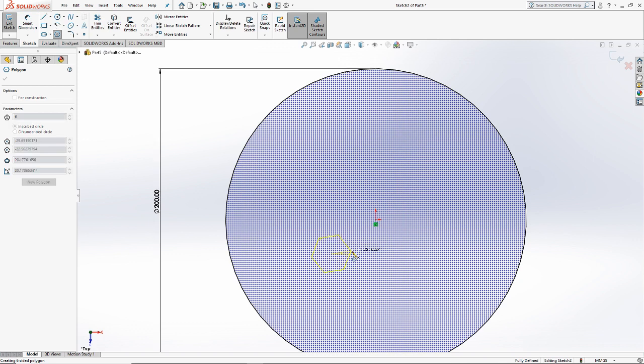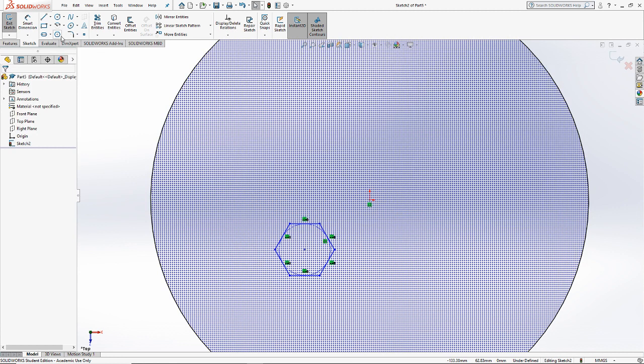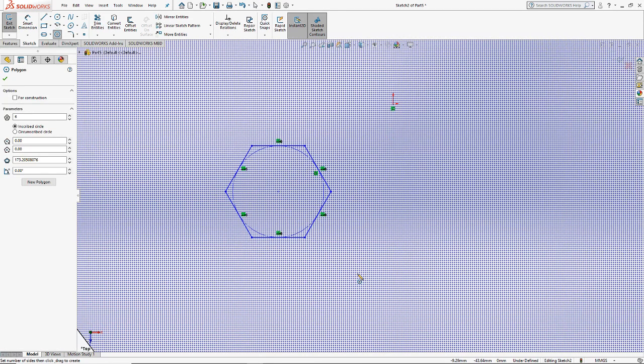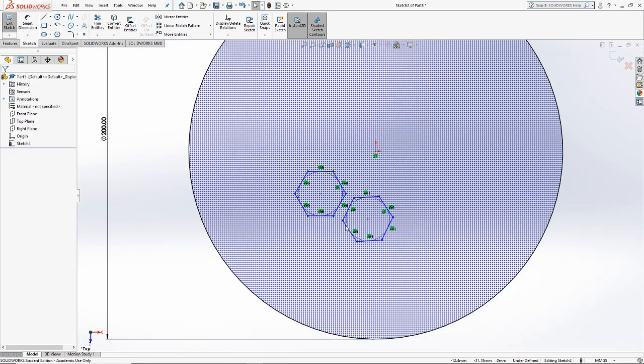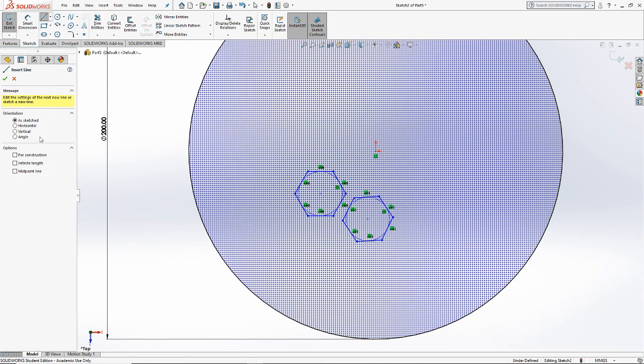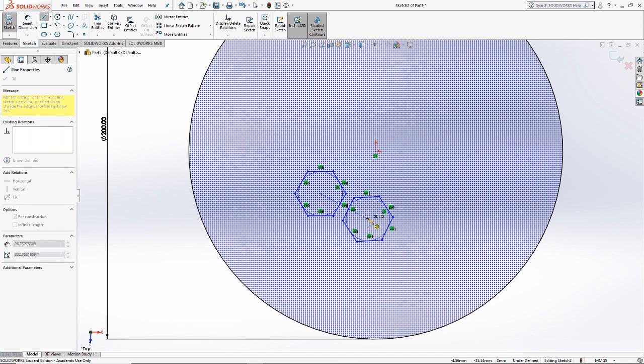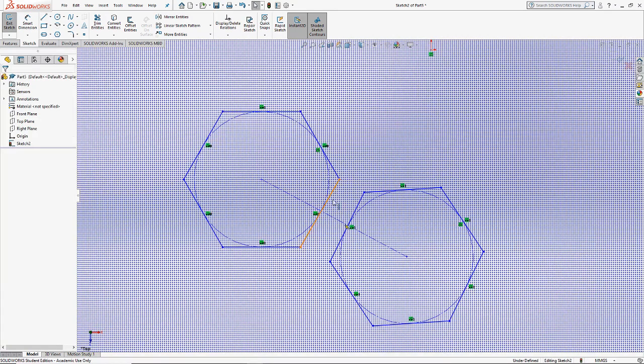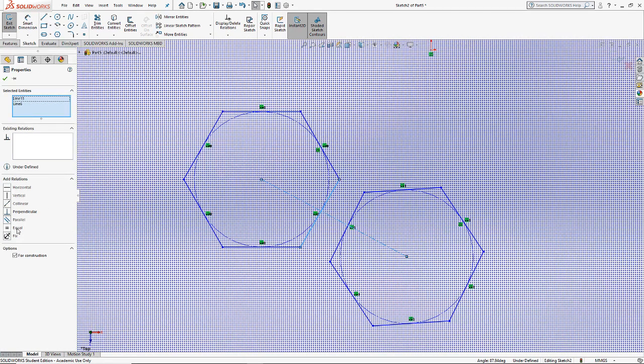So maybe you're 3D printing some texture that you're trying to use for solidity, or maybe you want to create a whole bunch of neat cutouts in a shape that doesn't need that much material. So if we were to create a couple of hexagons here, I could tell SolidWorks I want to establish a pattern.